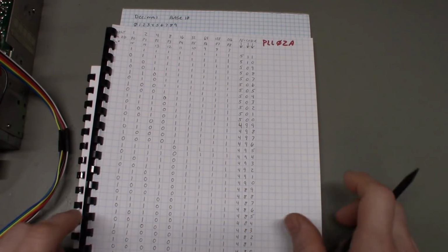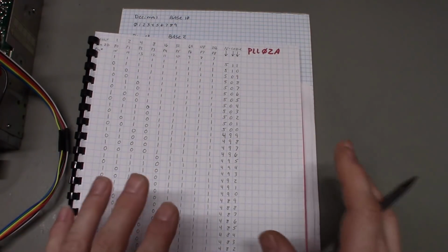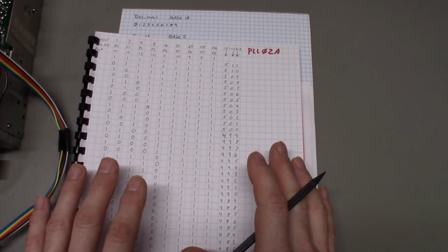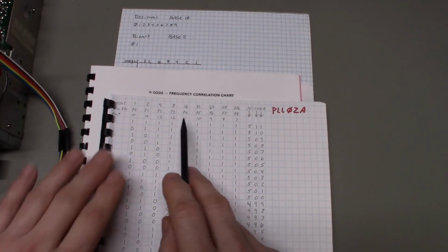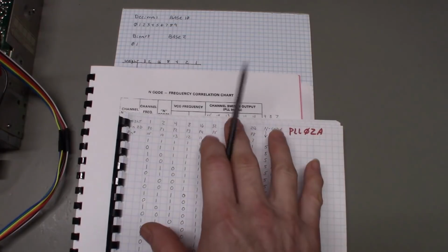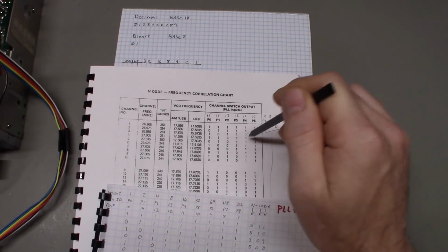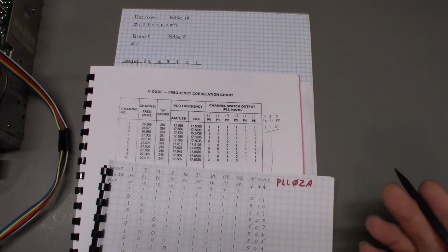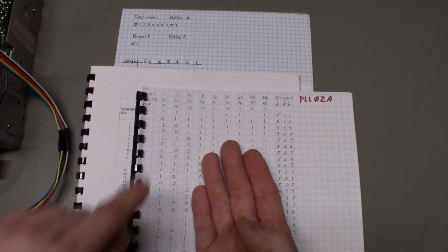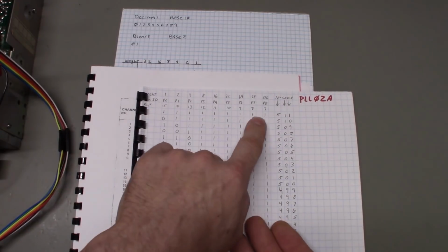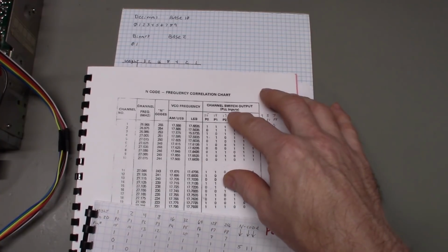But I have written one of these charts basically for most all of the common PLLs. The advantage is, it's a really handy little book because it has all 511 possibilities written out. And I say 511 because if you do the math. Now, in my book here, and this is another thing, if you're going to write one of these, I suggest you do like the manufacturers did. Write it backwards. I know that's not the proper way to write it, but the reason I write my charts with the binary flipped, so it's least significant digit first to most significant digit last, is because the factory did that in their service manuals.